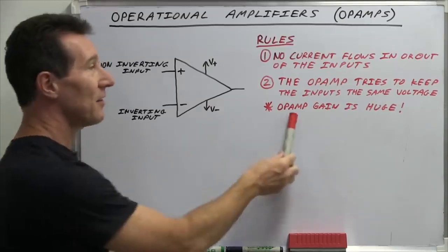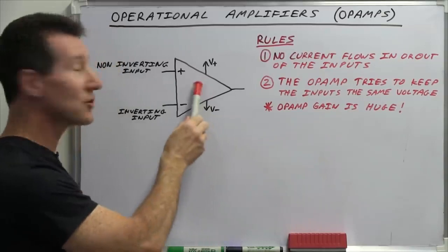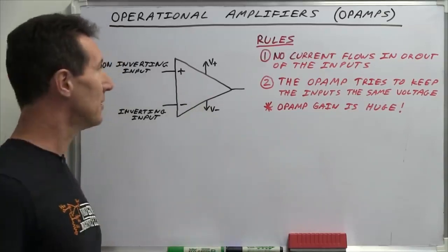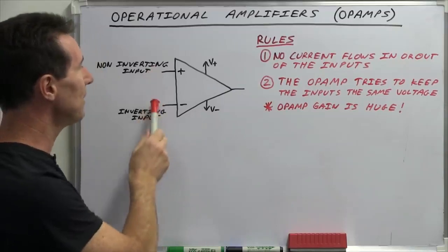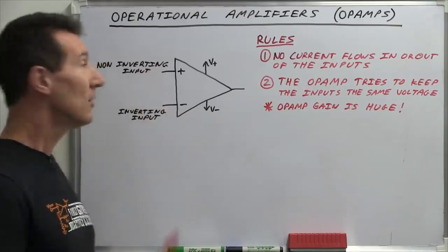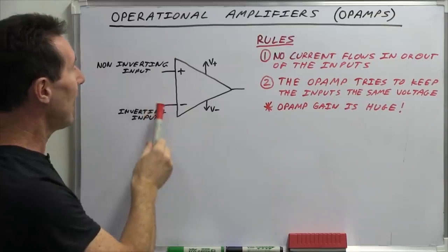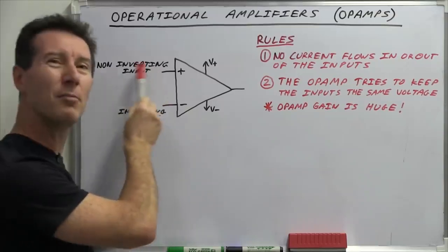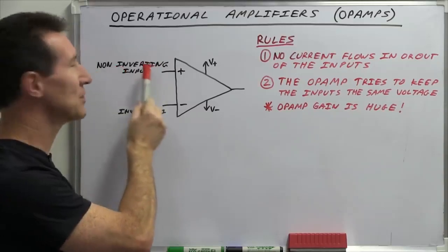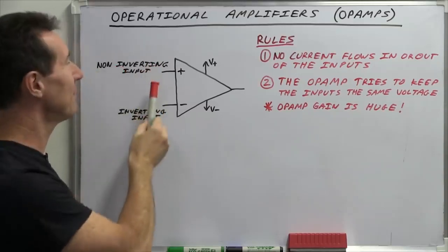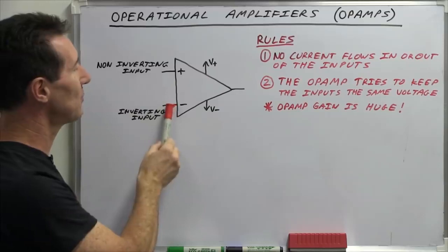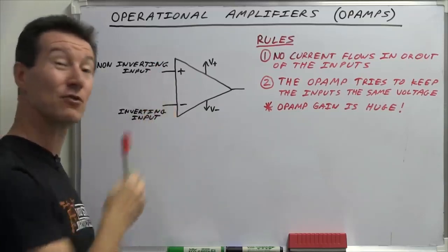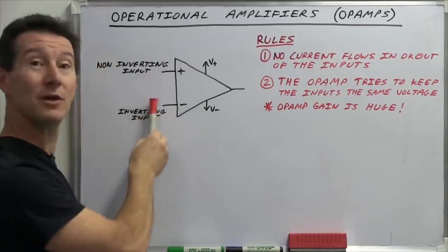So I mentioned that the gain of an op-amp naturally inside is designed to be enormous, almost infinite. So what happens if you just feed voltage on the input here? Well, let's assume that we have 1 volt on our non-inverting input here, and we have 1.01 volts, or slightly above, 10 millivolts or even 1 millivolt above this one here? Well, the amplifier will actually amplify the difference, or attempt to amplify the difference between these two inputs.